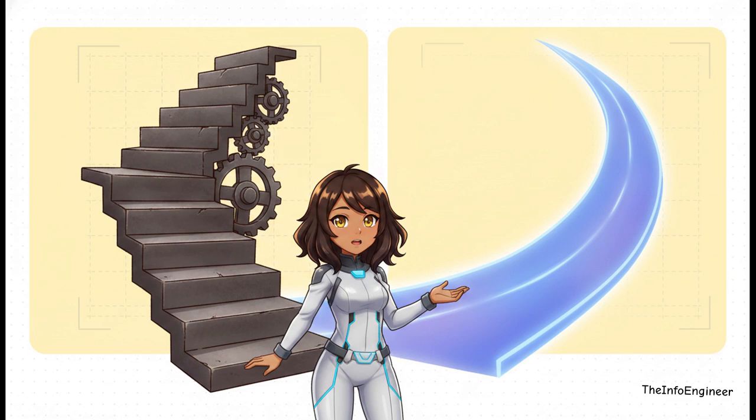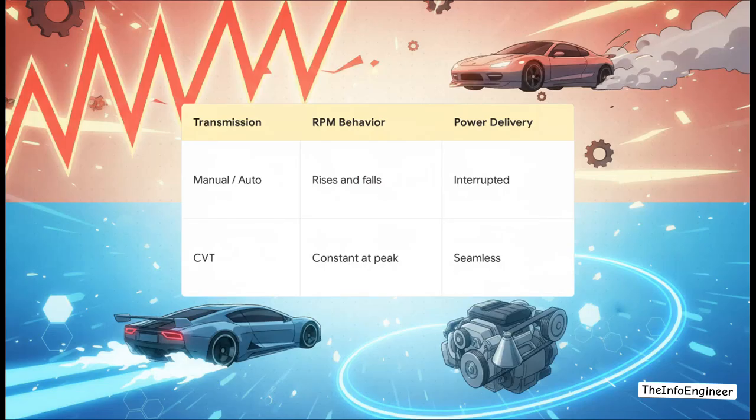But a continuously variable transmission, it's completely different. It's not a staircase at all. It's an infinite sloping ramp. This design allows for constant, uninterrupted upward acceleration. Because there are no discrete gears to shift through, the engine never actually has to drop its RPMs to move to the next level. And the real-world impact of that ramp versus the staircase is absolutely massive.